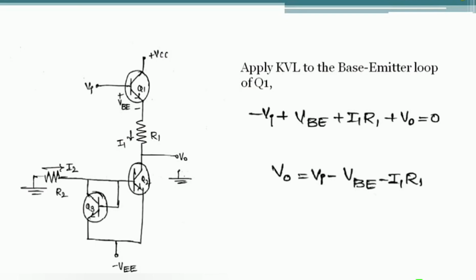Why we have to use a level shifter, in brief: the intermediate stages and the input stage are directly connected. Because of the direct connection of the two stages, or cascaded differential amplifier circuits without using coupling capacitors, the DC level is added at every stage in the output signal. Because of this addition of DC level at every stage, the signal is clipped at the output. Due to this, we would have to use a coupling capacitor.